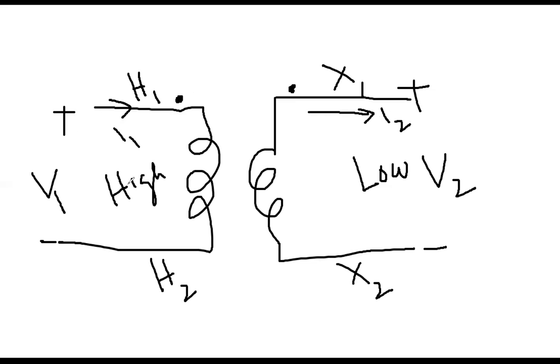Now, sometimes those dot marks are not given, or the plus minus signs are not properly mentioned, or sometimes incorrectly placed. To find out the correct polarity or the correct dot terminal, you can make a simple test. Everybody see, to make the test you just need a voltmeter.